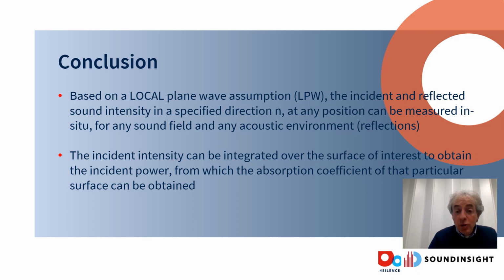So based on this local plane wave assumption, we can measure the incident and reflected intensity, and that is true for any sound field or any acoustic environment. We don't rely on any assumptions about the global sound field. And based on that incident intensity, we can integrate that over the surface, and from which we can calculate the absorption coefficient of that particular surface.